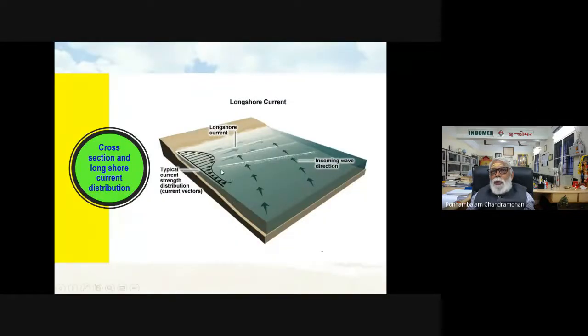And this, I already told you. When you see the littoral drift, we state the total quantity, but how is that quantity distributed across the subzone? This is where the wave breaking zone starts. Will it be constant till the water line or will it vary? So this is the quantity distribution across the subzone. At the middle of the subzone, you'll have the maximum volume moving. That extension of the sediment transport will be there even beyond the breaker zone to some extent, maybe up to 50 meters. This you can also see in the standard books. They give the distribution of the littoral drift across the subzone.